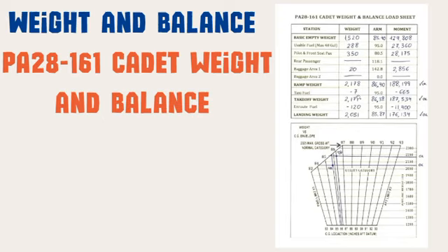So we have the baggage area 2. The arm is listed as 0 because there is no second baggage compartment, so it is not included in the calculation. Ramp weight. The total weight of the aircraft when it is on the ramp or parked. Taxi fuel. This is a standard adjustment provided by Piper, indicating a reduction of 7 pounds in weight and 665 units of moment during taxi.